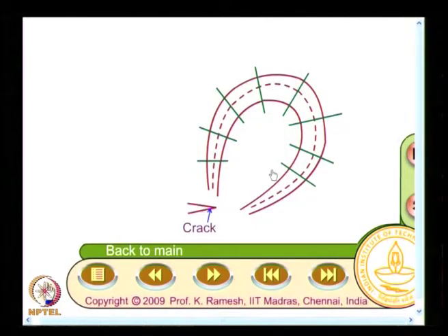once we developed a methodology, I should be able to apply it to fracture mechanics problems. That is one of the very important practical requirements where experimental mechanics is needed, and you have fringes of varying thickness only, and you need to make a decent sketch of it. You need to find out, see, because if I do a scanning like this, I will not be in a position to pick out the exact minimum intensity point. So, I must find out the edge normals and then do the scanning, and this becomes mind boggling how to implement this kind of a scheme digitally.